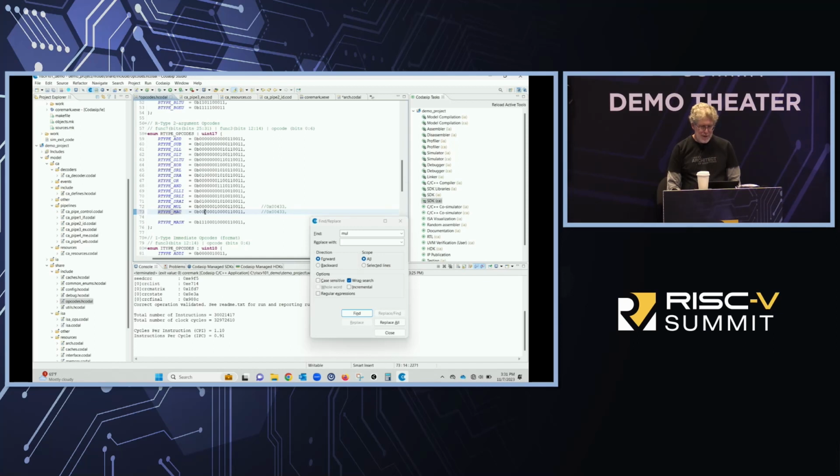And make it different. Let's see, just make it 1, 1. So now I've created it. Like I say, if I was really doing this for work, I would actually look at a custom instruction, because a MAC is a custom instruction in RISC-V, and create my own based upon the definition of RISC-V custom instructions. So now I've just created my opcode for my MAC.